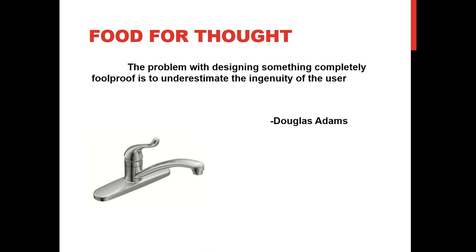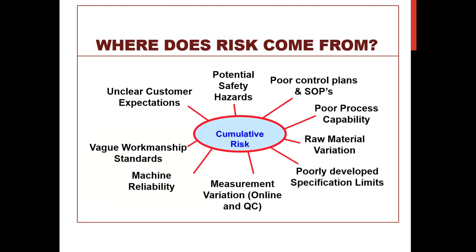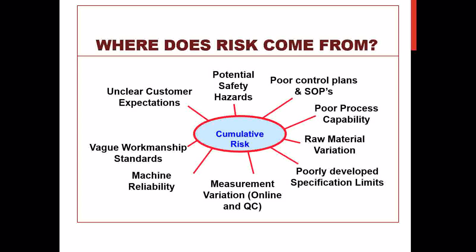So there's our options as a design engineer. We can either eliminate the cause for injury or warn against it. Our preference, of course, is to eliminate. And this is why we do design FMEAs, to help us anticipate these problems and get them designed out of our product.